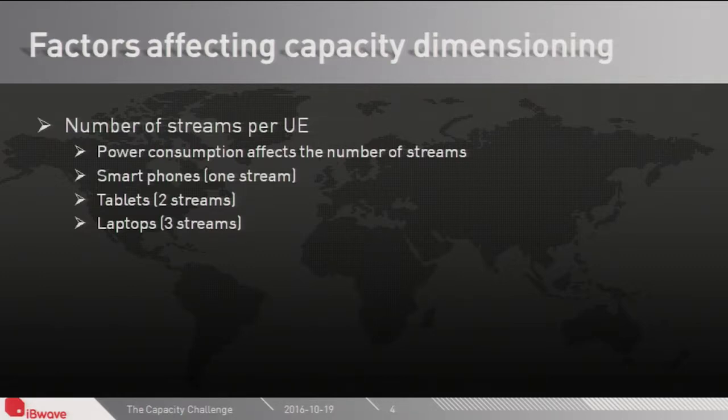So what does it mean? Well, if you have your 3x3 MIMO AP, that's all good and nice, but what happens if this room is full of smartphones? That means that I'm not going to be able to get that advertised 3x3 3-stream MIMO data rate. Not anywhere close, because all of my devices are going to be 1-stream devices. So knowing what happens out there as far as the devices are concerned is of great help.